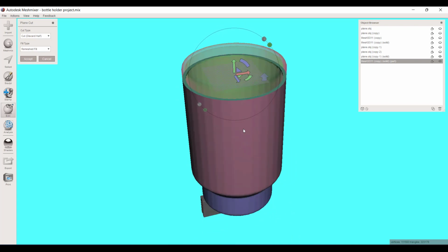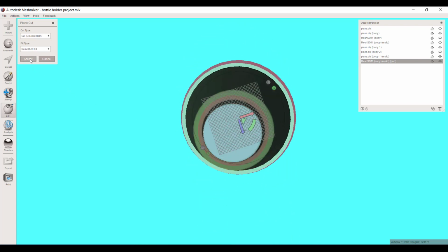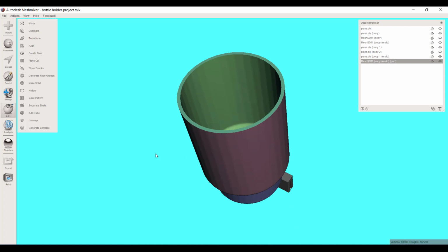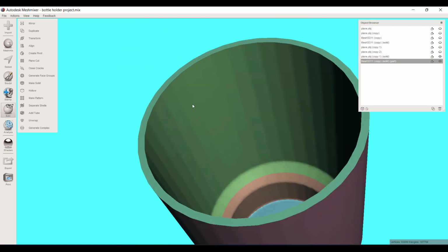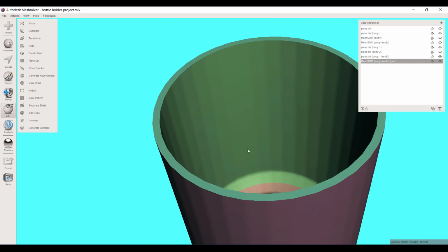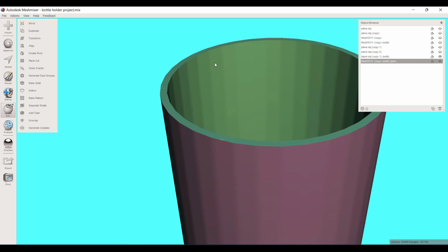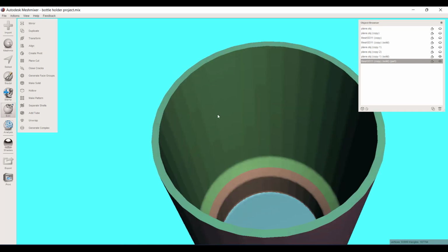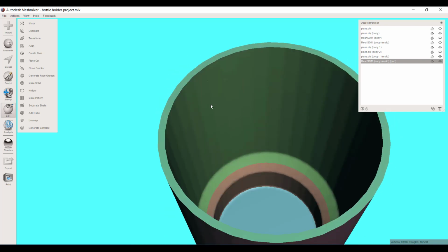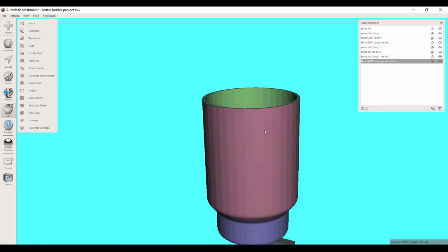And I want to discard the upper half. If I hadn't flipped this internal surface inside out, then all of this internal here would be that candy cane striped color because the mesh is flipped 180 degrees from what it should be. This is actually a solid part. It's got an internal surface and an external surface, so you need to have those meshes facing the right way.